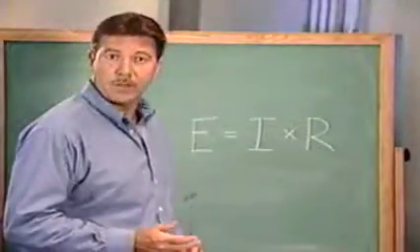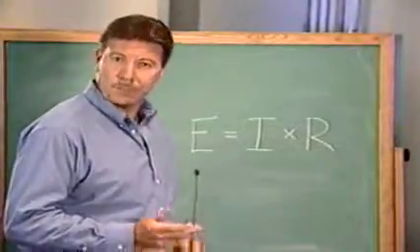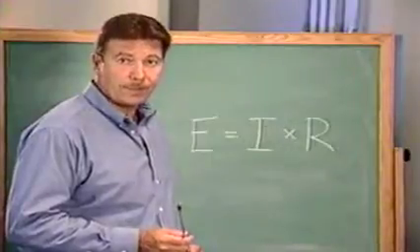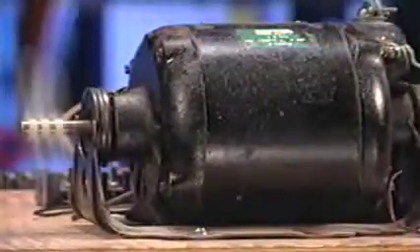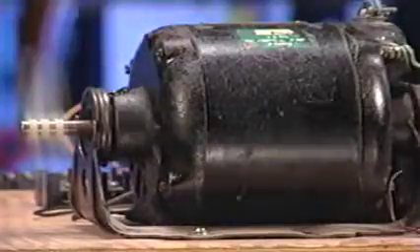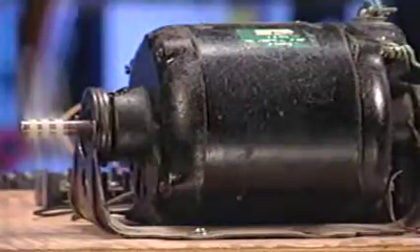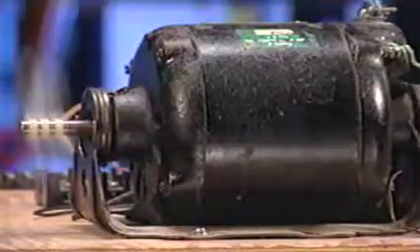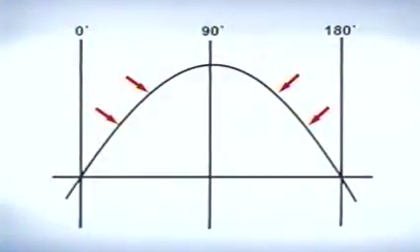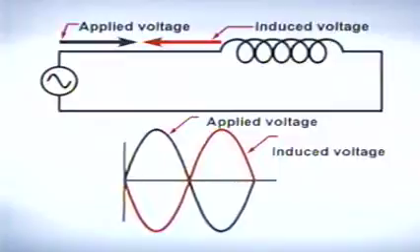From an earlier discussion of Ohm's law, we mentioned that there is a predictable relationship between voltage, current, and resistance. This relationship is somewhat altered when we deal with AC current flowing through circuits that have inductive loads, such as motors or solenoid coils. The changing voltage in an AC circuit leads to changes in the strength of the magnetic field. These changes in the magnetic field produce a second voltage called induced voltage, which counteracts the effects of the original supply voltage. The supply voltage must first overcome this induced voltage before current can flow.